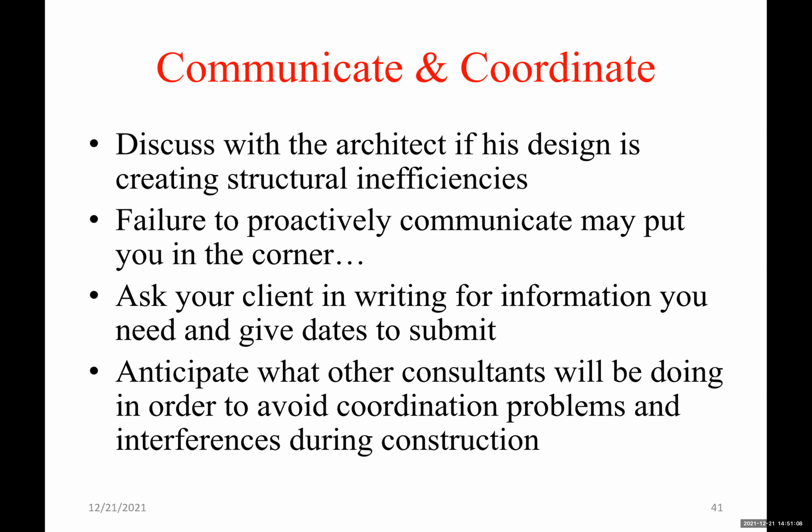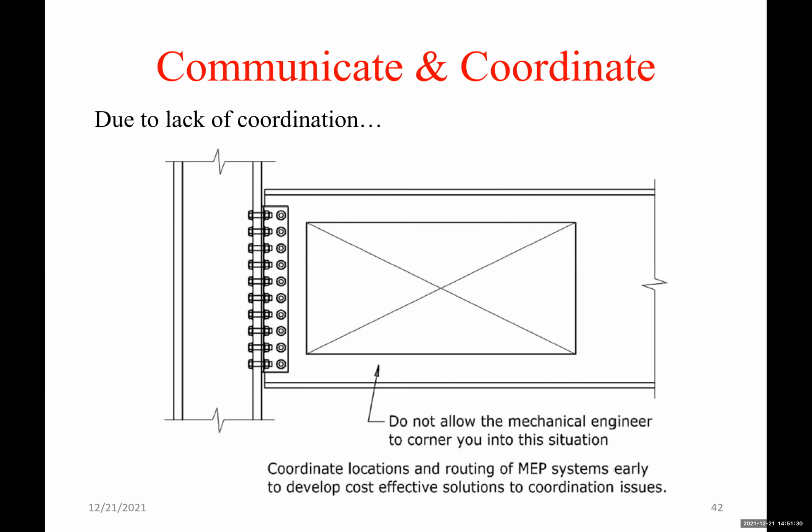Anticipate what other consultants will be doing in order to avoid coordination problems and interferences during construction, right? So MEP, architect, that's, I think, what's most important for the structural engineer, to coordinate with them everything to avoid any problems during construction, such as this one. So you have a big opening at the end of the beam to run a duct for a mechanical engineer. Okay, look, this is a deep beam. Most of the web is gone. So this is due to lack of coordination.